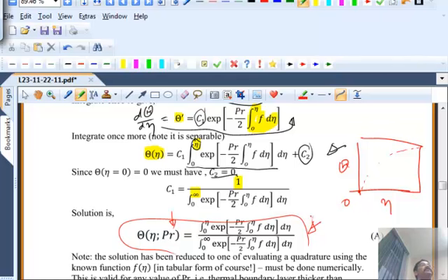My question is, how would you go about doing that? What would you need to do? What information would you need? The Blasius solution, you take that table and put different values of eta. Exactly. So I have to give you the table. And if I say for eta of 0.1, you will put this limit as 0.1, okay, and find that integral up to that point, and put that again into that expression, the whole expression, and do the integration again.